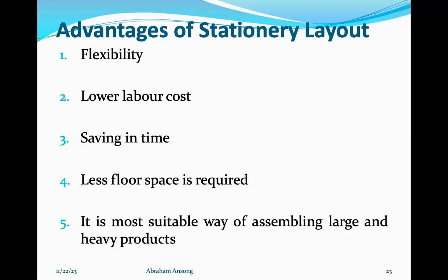There is savings in time because there is no movement. Everything that you need will be brought at that particular place, so no time is wasted in moving the semi-finished products from one place to another. Less floor space is required because all the manufacturing or production is done at just one location, so the floor space required is normally less compared to the other types of layout. It is the most suitable way of assembling large and heavy products. I think we explained that at the very onset.